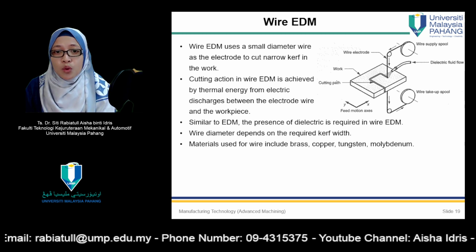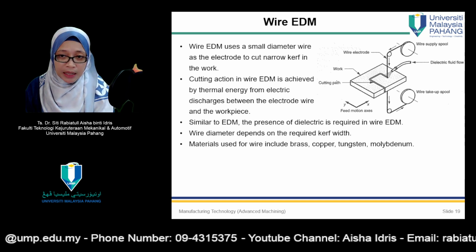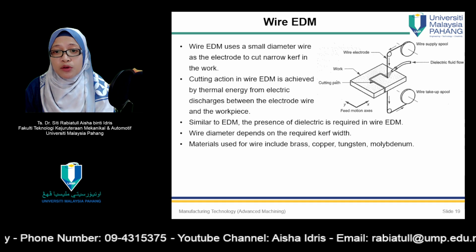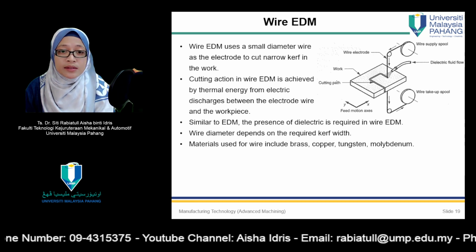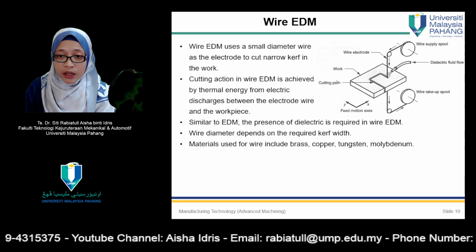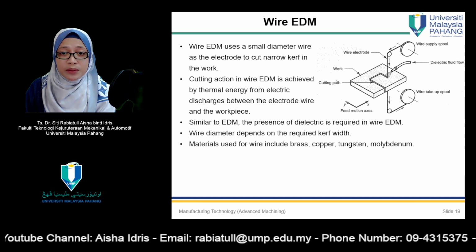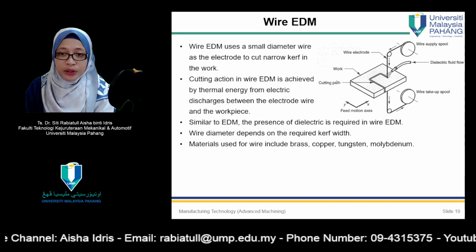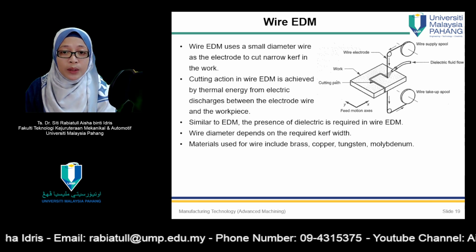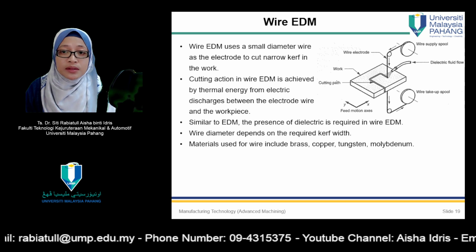Electric discharge wire cutting, EDWC, commonly called wire EDM, is a special form of electric discharge machining that uses a small diameter wire as the electrode to cut a narrow curve in the work. The cutting action in wire EDM is achieved by thermal energy from electric discharges between the electrode and the workpiece. The wire EDM is illustrated in the figure here.